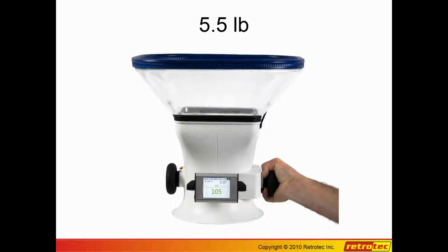Cool thing about it, 5.5 pounds. There are various hoods. This one here is 8.5 inches. This is 16 inches, and so on. And you can see, quite easy to hold in one hand. It'll run all day on a battery charge. You have to buy batteries for it. Stores all the information right in the device if you'd like to. It'll show you values in CFM, cubic meters per hour, liters per second, whatever you want. It's also measuring barometric pressure, humidity, all that kind of cool stuff.